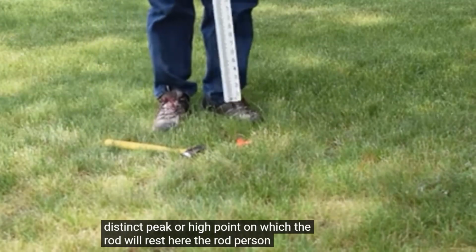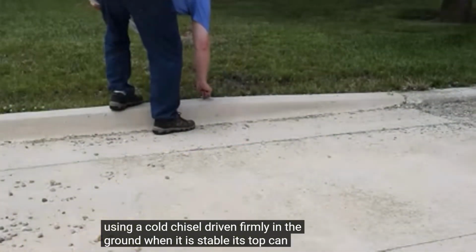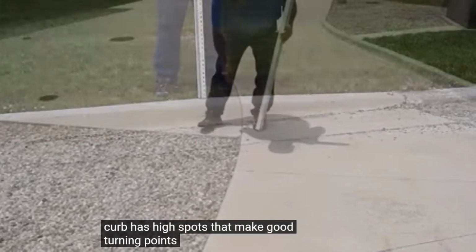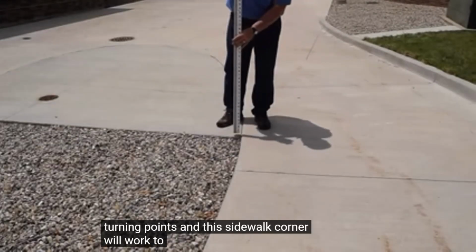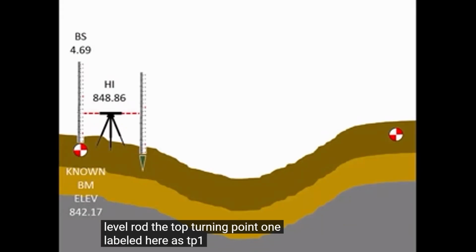Here, the rod person is using a cold chisel driven firmly in the ground. When it is stable, its top can have only one elevation. We can put our rod on high spots that make concrete turning points, like concrete curb elements of construction. This sidewalk will work too. The rod person will draw a cross or another sign on top of the turning point and label it here as TP1.